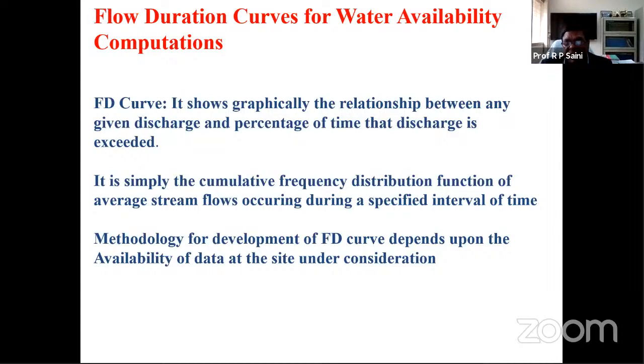So accordingly, you have to consider, and I think it's clear to you that if you are dealing with a very small capacity, say 5, 10 kilowatts, and you want to install hydropower locally in decentralized mode, don't do this exercise. You just ask the local people what the variation is, and based on that you can fix it. But if you want to develop a conventional or larger capacity plant, then you have to be very careful.